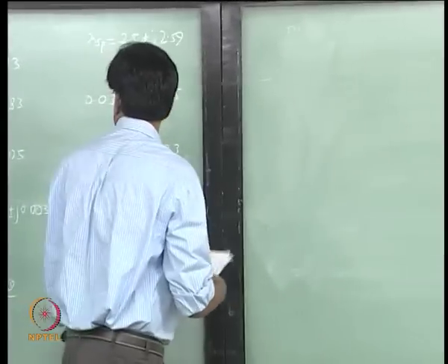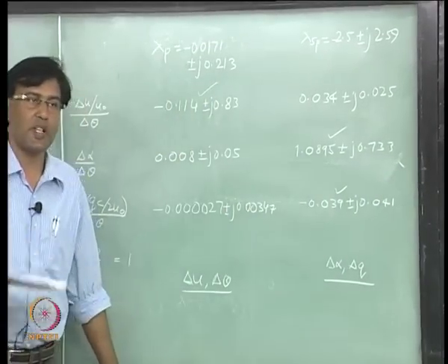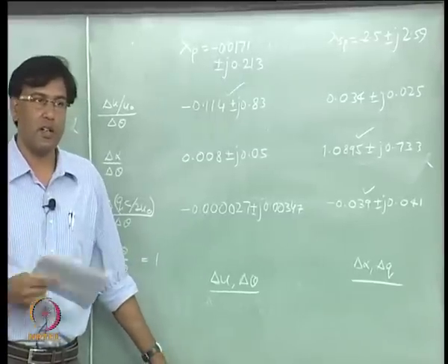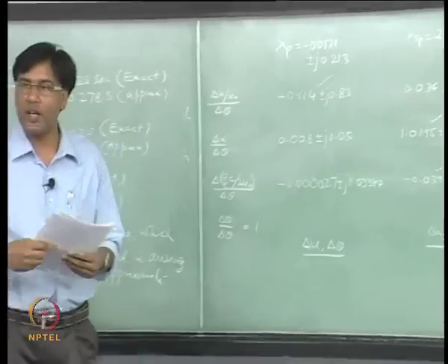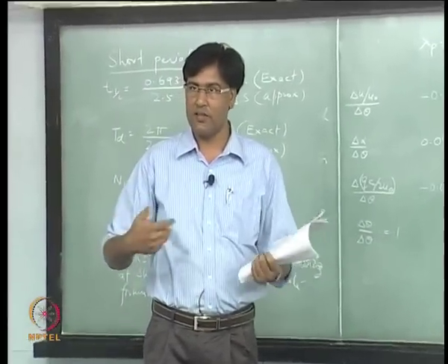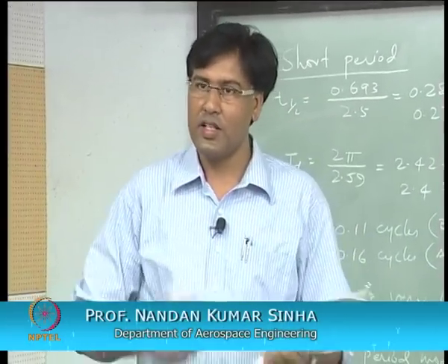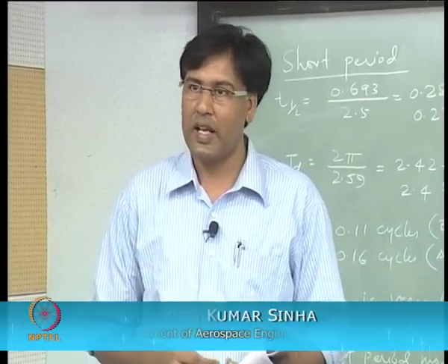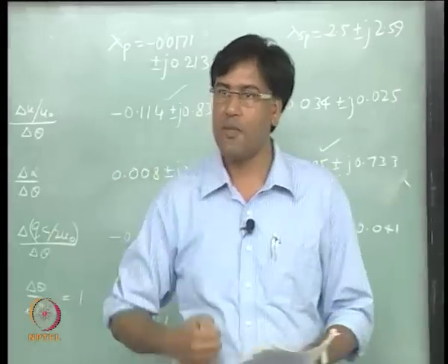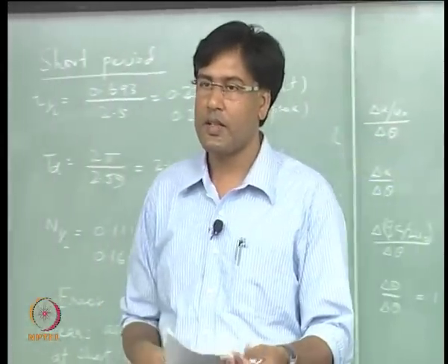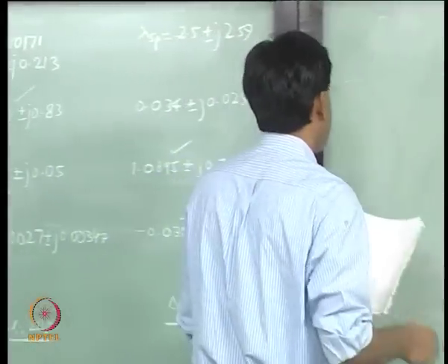Try to look at now the variation of these eigenvalues in the complex plane when you change something on the aircraft, right, and one of the things that you can easily change is the CG, right. Sometimes there will be a block of masses just for balancing out the aircraft, right. So, dead weights inside the aircraft can be used to change the stability property of the aircraft.